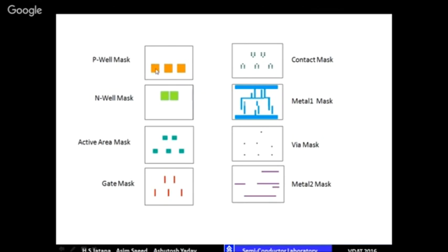In this area, some portion I will define as active area, which is green in this shade. You can see this is smaller than this. So there will be some active area, and in this active area we will define the transistor. Active area is the area where components will be made. The rest of the area is field area, and this is the poly you can see here.